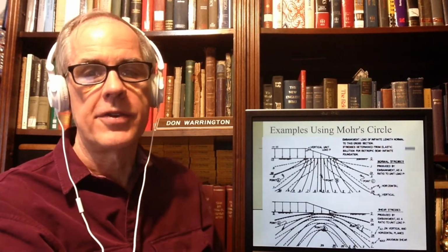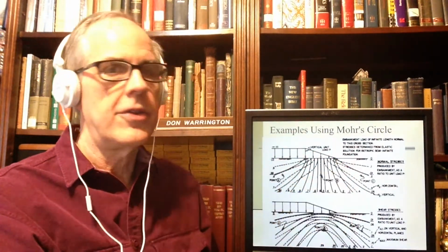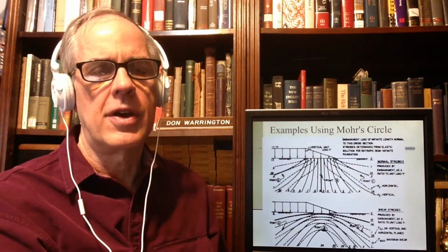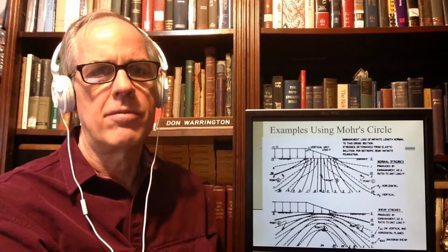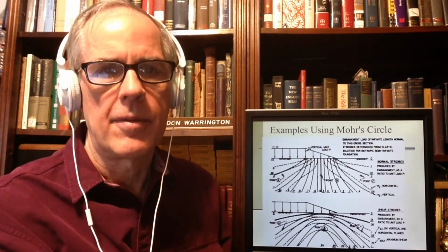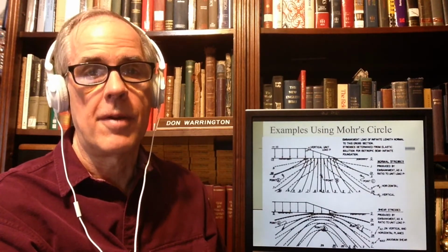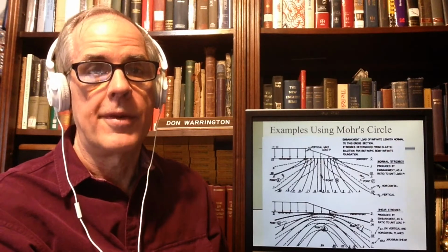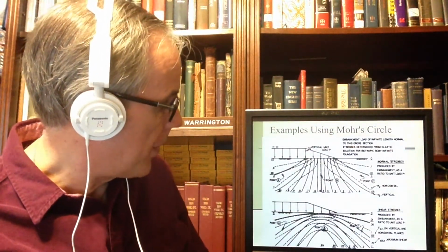In the meanwhile, we're going to talk about the stresses of that. If I start with a level ground and I add that as an embankment, I'm going to induce some fairly complicated stresses. And this is a problem which your Soils and Foundations manual talks about briefly, and I don't get too much into that because it gets into a theory of elasticity problem, one of the most celebrated ones in soil mechanics.